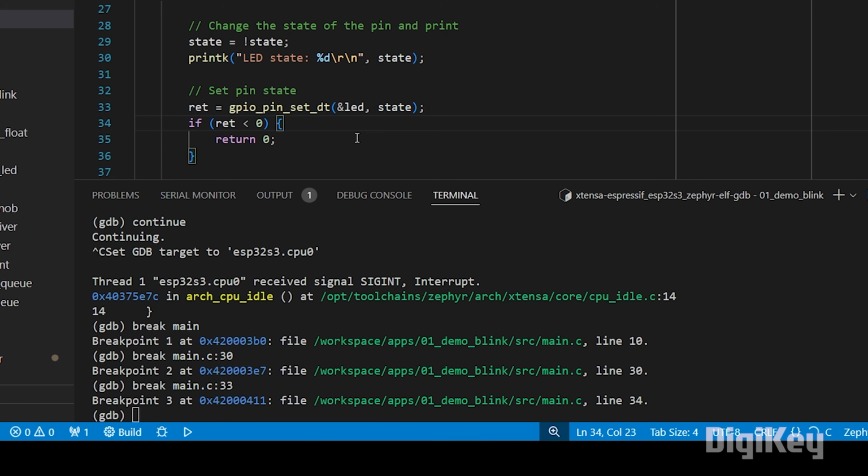What you'll find is that the compiler will often optimize away lines. So this line might not exist in the compiled code because the compiler optimized that away. Feel free to dig into the compiler settings so you can try optimizing to different states, because compilation is usually set to optimize for generally space or speed when dealing with embedded systems. I won't dig into that here because I'm just demonstrating how GDB and OpenOCD work so that you can start debugging.